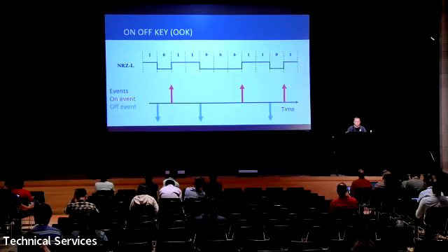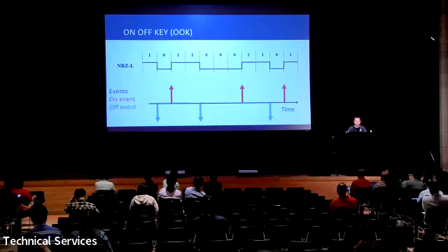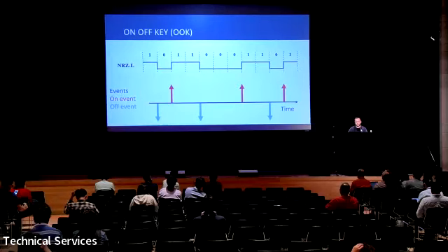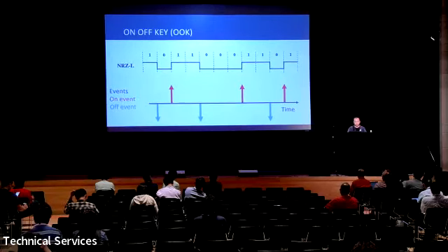This top row is the intensity ground truth, and the bottom one is how the events are generated corresponding to the intensity values. But different from standard OOK modulation, we are watching the up and down edges, because only when the intensity goes from 1 to 0 or 0 to 1 will it produce events. So we are actually doing the demodulation from the edges.